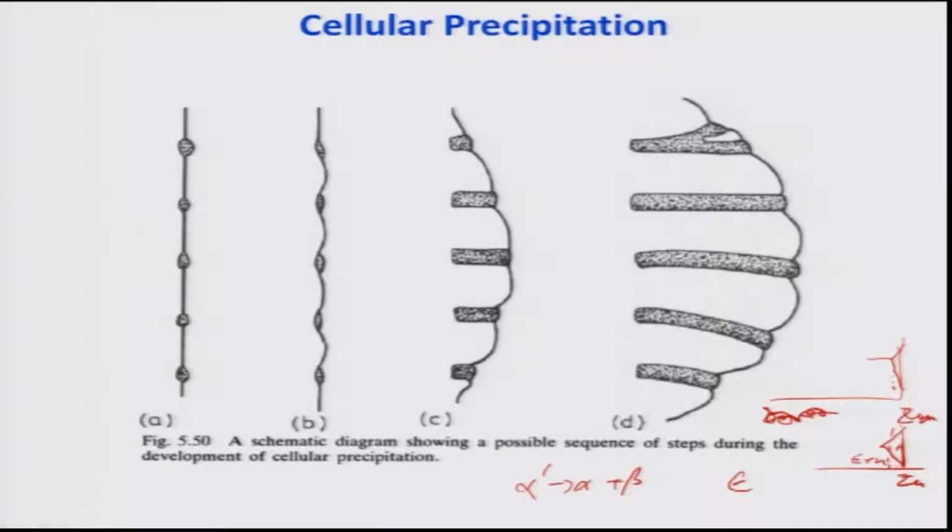Now, if the sample is quenched, from 400 to 200 degrees Celsius, not heated, that is, completely heated up to 400, solutionized, then quenched to 200 Celsius, then this kind of sheets or plates of solute-depleted eta and epsilon phase will form.